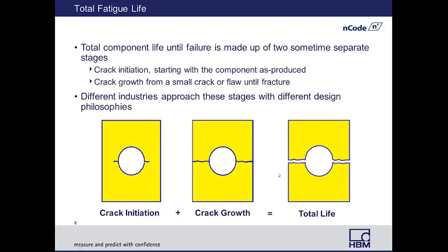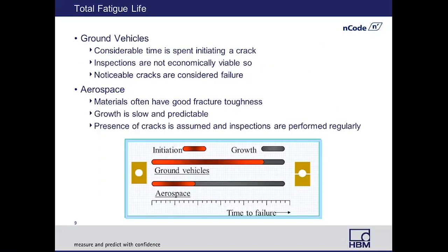Now there's a couple of philosophies in terms of how you actually design for fatigue. We're going to talk about that. They deal both with crack initiation and crack growth, but you could actually consider the total life of a part, assuming that you're taking it all the way to failure, to be the summation of life in crack initiation and then the crack growth phase. So summing those two together is going to give you total life. And let's go ahead and take a look at a couple of different philosophies.